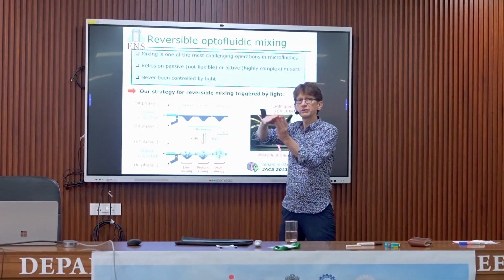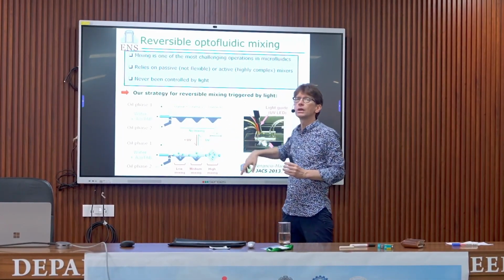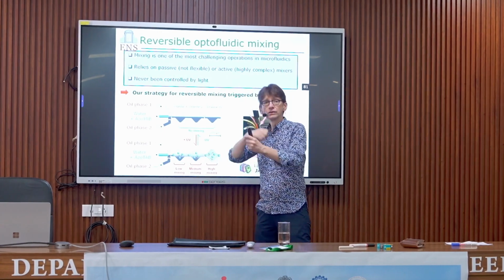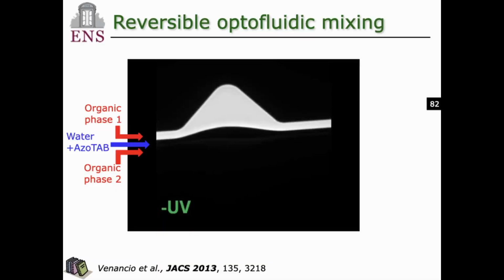These two compartments will be in contact, but we are at high Peclet number. It means that they will not mix easily, but our droplets can move and they can work as a stirrer. So we can mix the liquid like that.